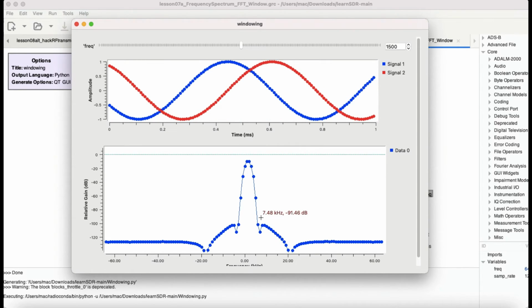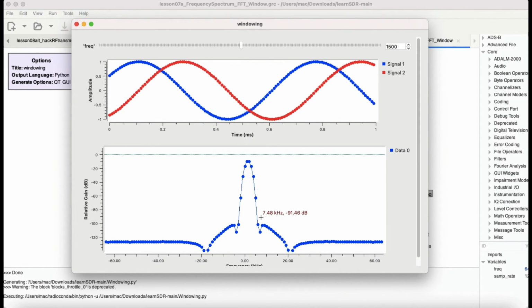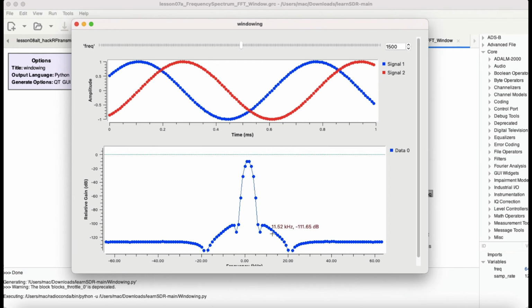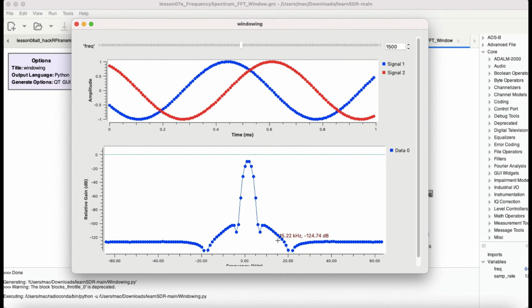First of all, let's say you capture a signal, and your signal contains a very strong interfering signal near your frequency of interest. You need to choose a window with a low maximum side lobe level. So this is how you're going to select your window.